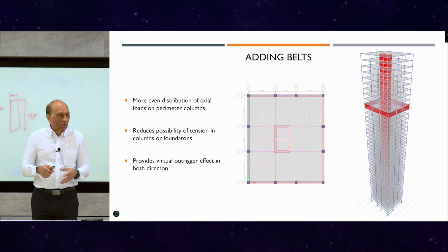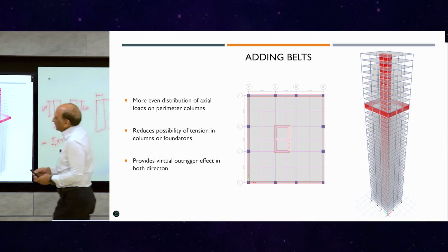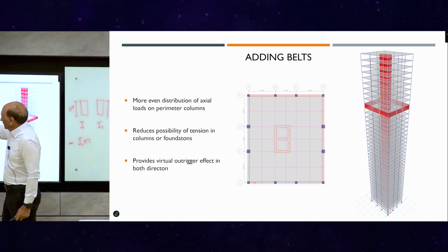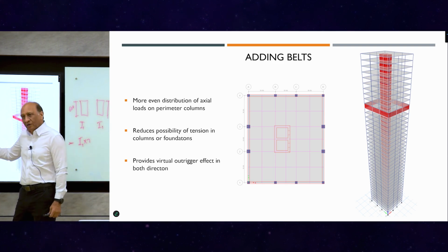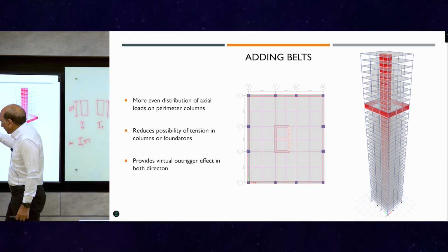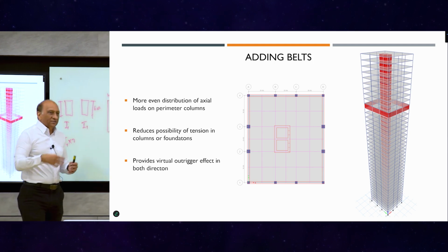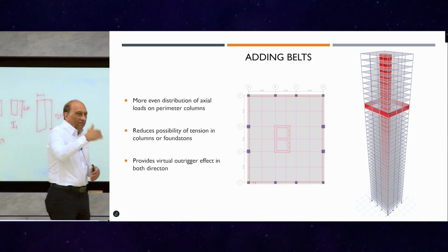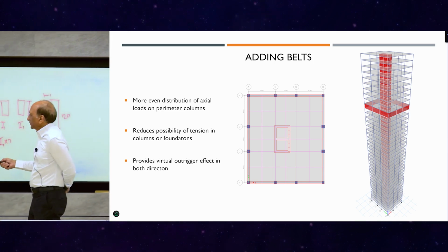So we need that core wall through which the whole system is connected. So this is the final virtual outrigger with the belt acting both as a belt and outrigger here. Sometimes you can put outriggers and a belt together, depending upon availability. Sometimes you can combine trusses with walls, with all that. All options have been used.